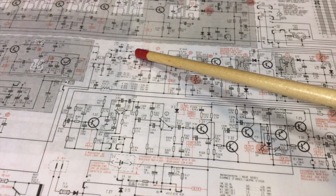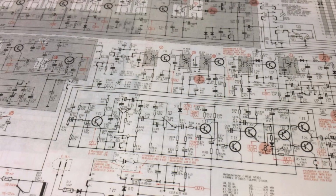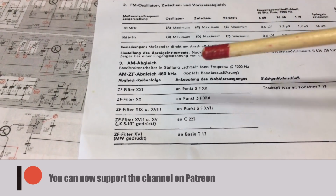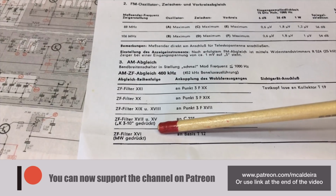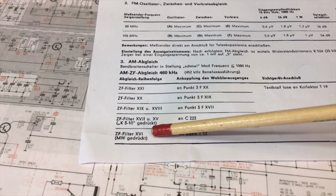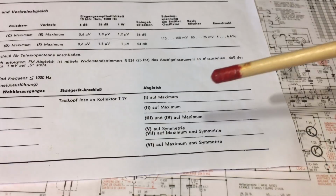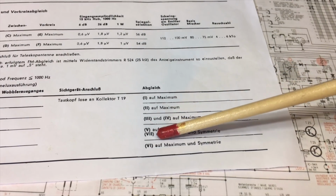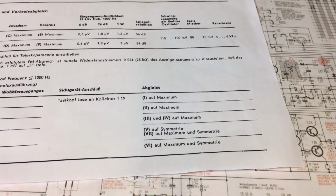Now they tell us to go further back because there are a few more filters we need to tune. And this is where things get a little bit more complicated. For example, here they tell us to tune filters 17 and 15, we need to press K3 or shortwave 3 to 10, and we need to feed the signal on capacitor 223, and then we're supposed to peak those points 5 and 7. Now this is where it got a bit confusing for me.